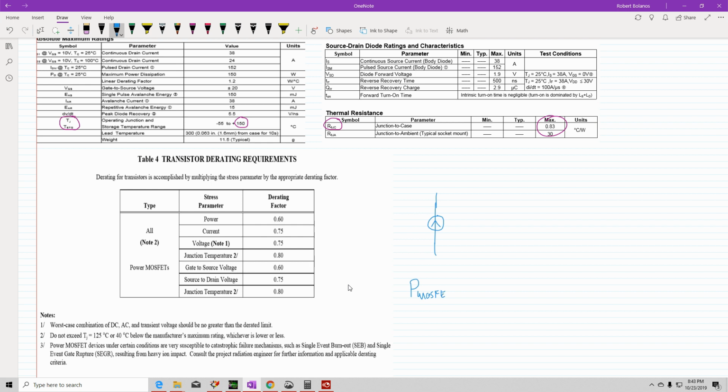To do that, we simply put a voltage source, and this is ground, negative, plus. Since the board is assumed to be at 25 degrees C, the analogy is to make this 25 V. In other words, your voltage source is going to be 25 volts.